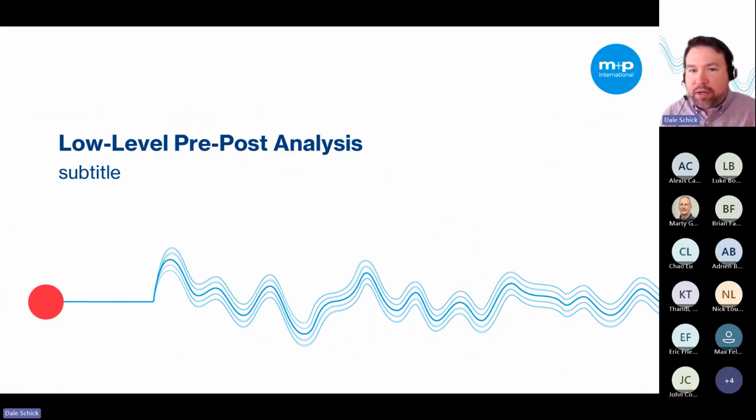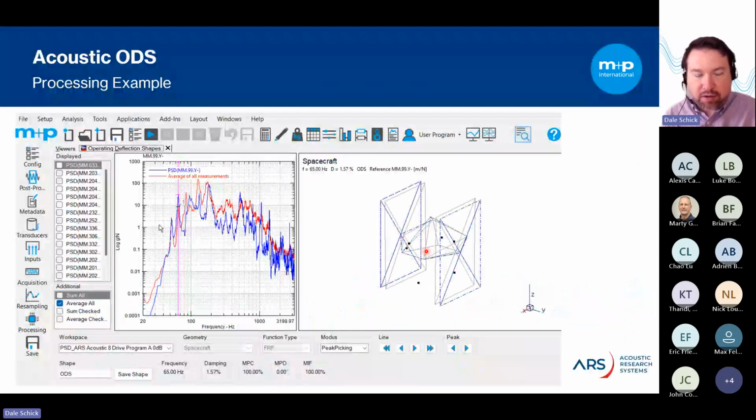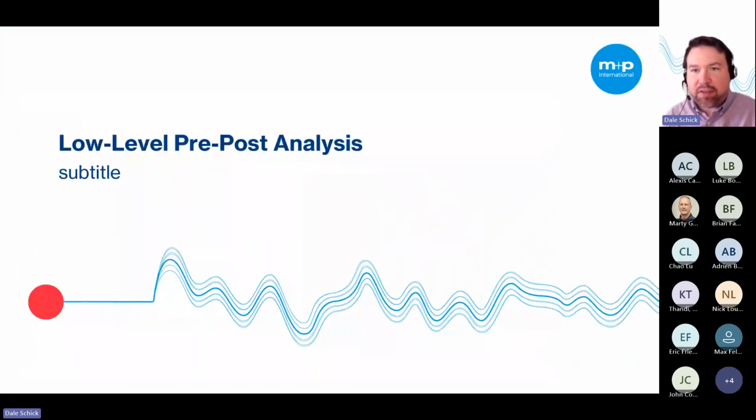So now we're going to take a quick look at another feature of recording all this acceleration data that we saw on our modal test. The standard PSD can also be used without being heavily processed in any way, just for a more routine operation. And this operation is known as a workmanship test. A workmanship test can help you determine whether or not your structure is assembled properly, right?